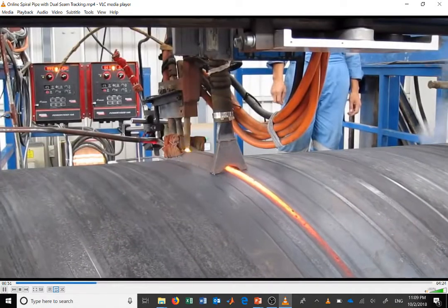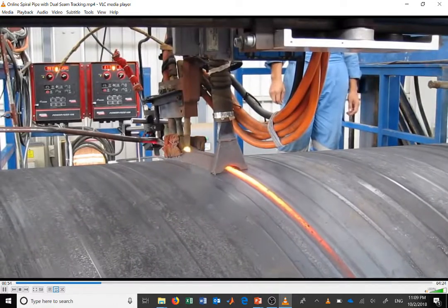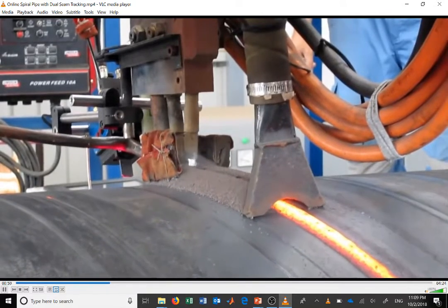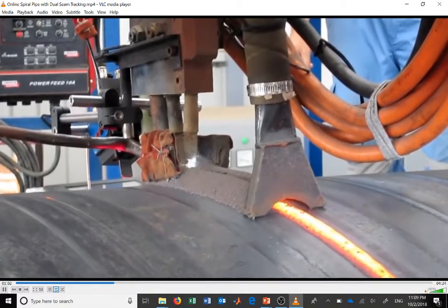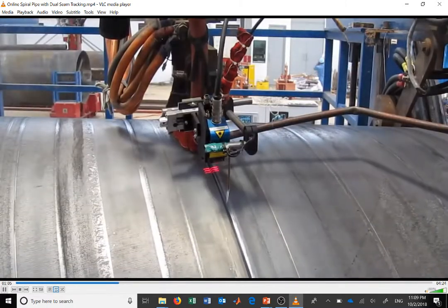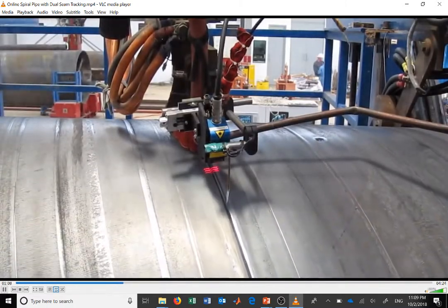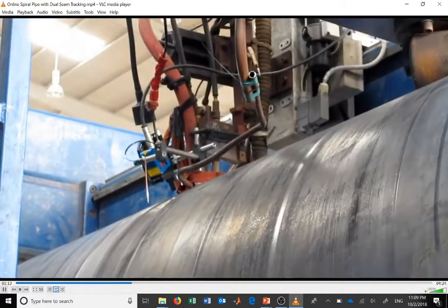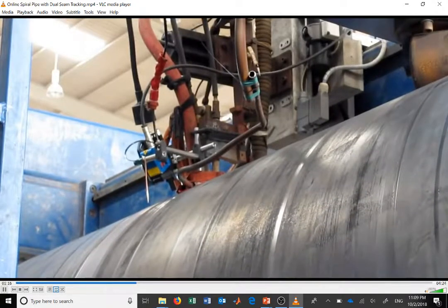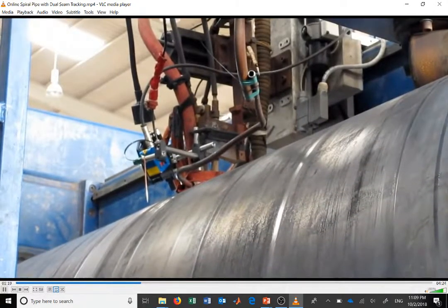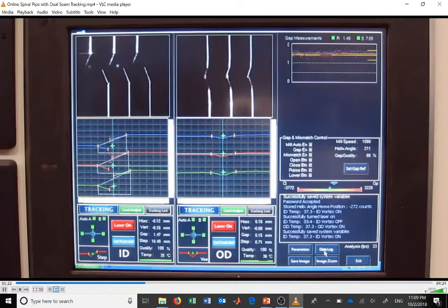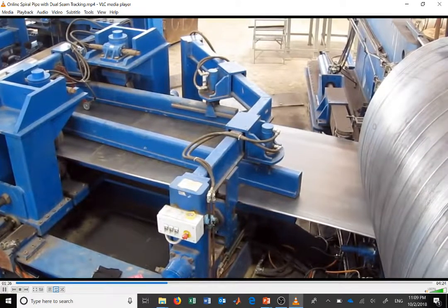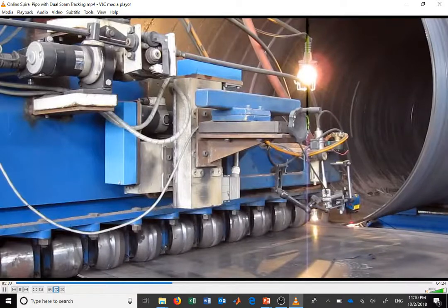The arc of the weld is submerged underneath this flux, and basically it's a powder flux that helps the electrical conductivity of the material, and it helps with a number of other chemical properties of the steel and of the weld, and it also keeps splattering and other things down. So anyway, submerged arc welding, SAW welding, and let me skip ahead a little bit more because there's a couple of shots here that show you a little bit more how the coil comes in and rolls up.